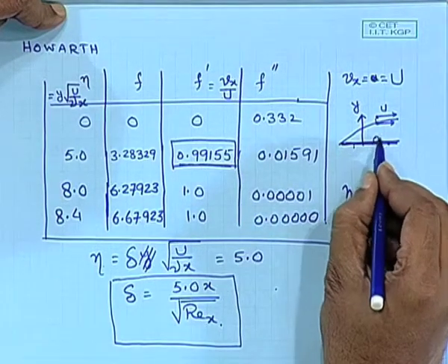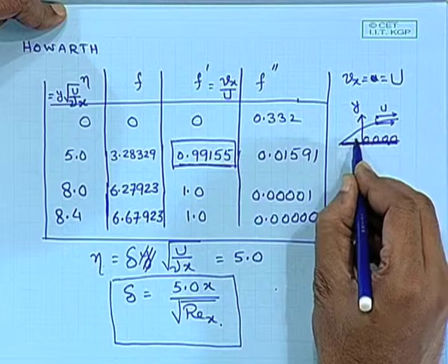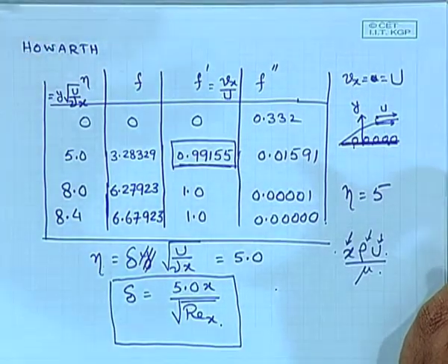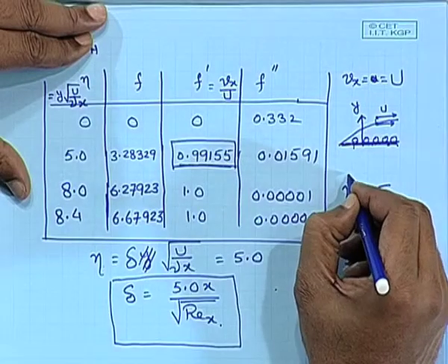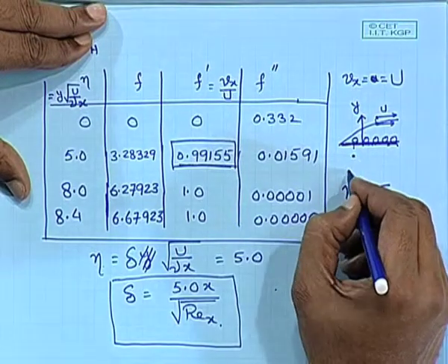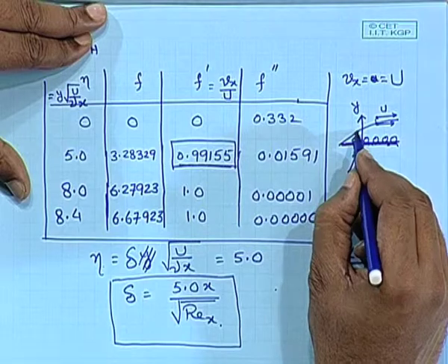So, what is happening at this point in terms of shear stress? We should like to find out its value, and you can see that shear stress is proportional to velocity gradient, which we all know for a Newtonian fluid. That velocity gradient will change depending on where you are in axial position, because if you are here, then the velocity changes from 0 to u infinity within this distance only.